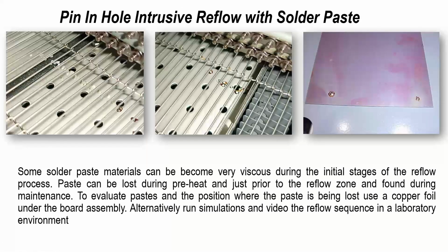Now, I mentioned on a couple of occasions the use of intrusive reflow, and you probably get the feeling that I kind of like the process. And this is just an example of a production line I was running, on this particular occasion. And I was trying to show how paste drips off of pins as it goes through reflow, particularly if you've got a large volume of paste. And you can see here how one paste performed not as well as others on some of the testing.